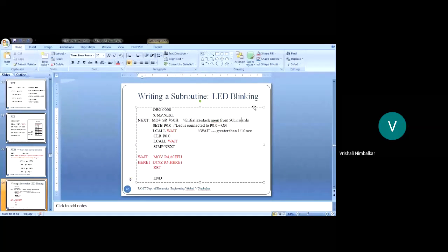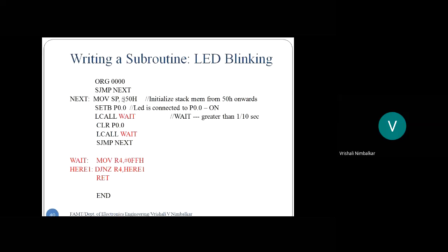Okay. Right. Now that bank and stack memory overlapping is gone. So never forget initializing the stack pointer whenever you're using call, return, push, pop, and interrupts. Right? Are you getting me, students?